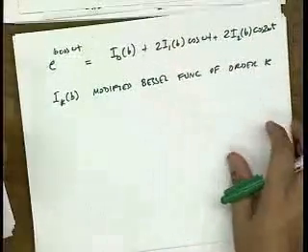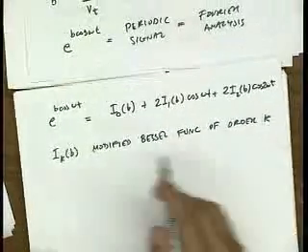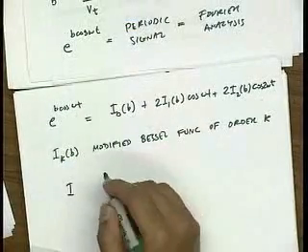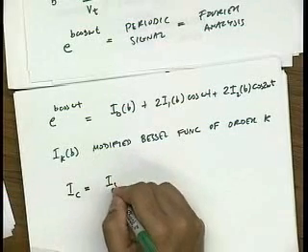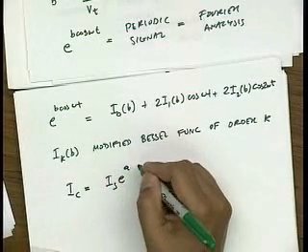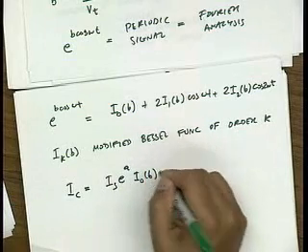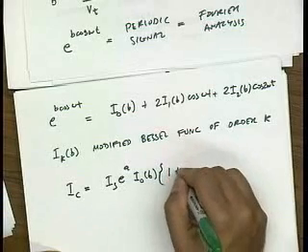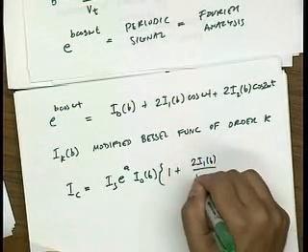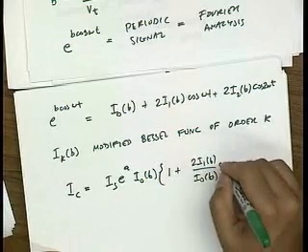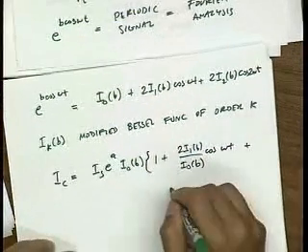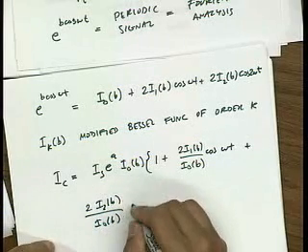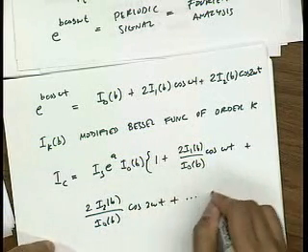Okay? So given that we know that e to the b cosine omega t gives us this series, we can now write the collector current in general as e to the a I0(b). I'm just going to factor out this constant term, times 1 plus 2 I1(b)/I0(b) cosine omega t plus 2 I2(b)/I0(b) cosine 2 omega t, and so on.